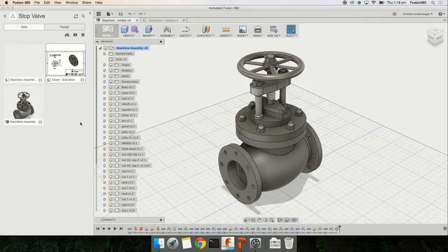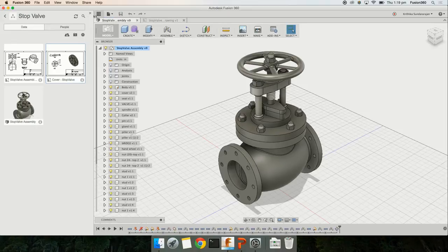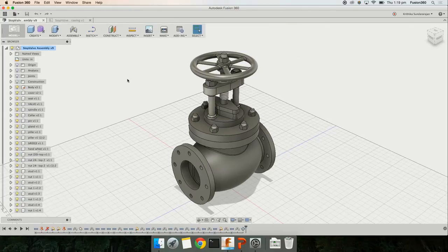And that's the same for the modeling environment too. So if you go to the model and related data, all of the drawings that are created from it, you can see from that option. Okay, so let's close this. So the drawing that we just created is fully associated to the model. So when you make any changes to the model, you can update the drawing as well.